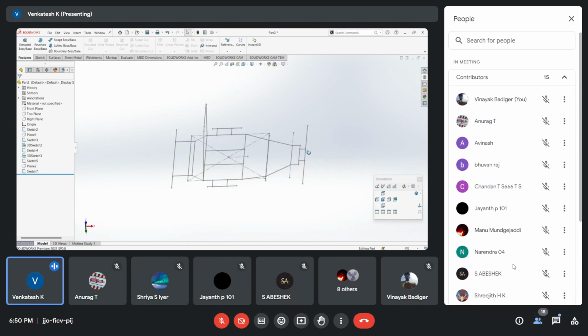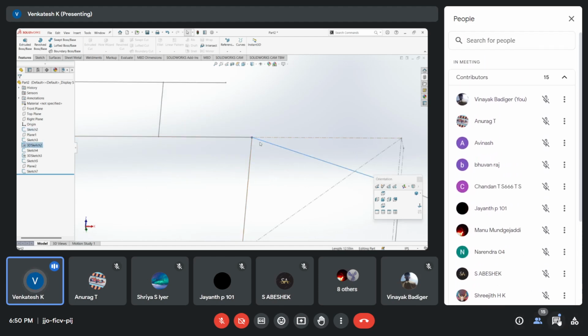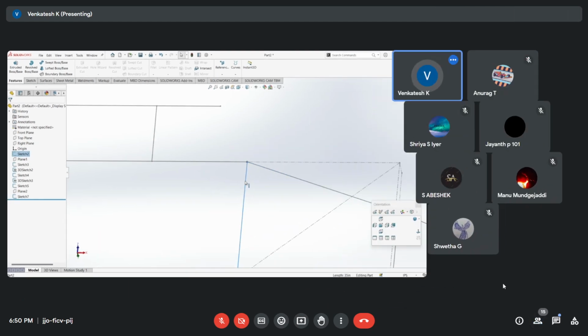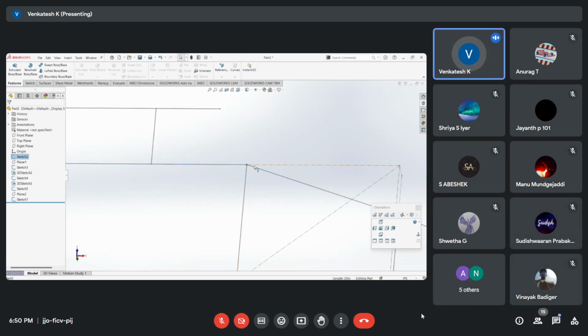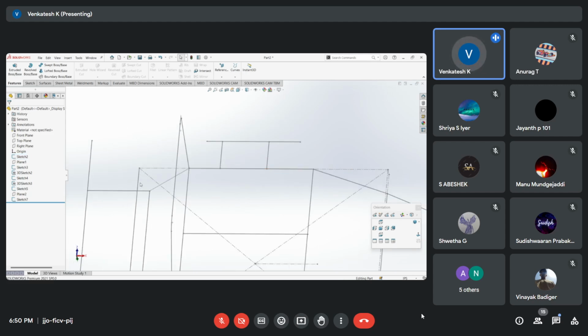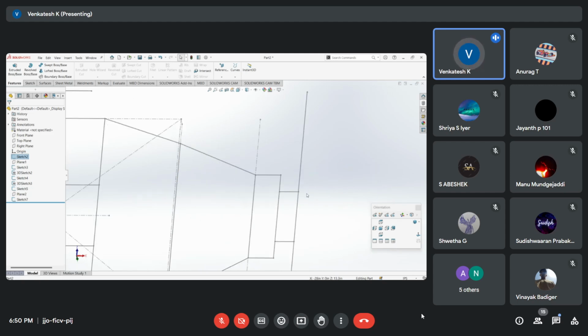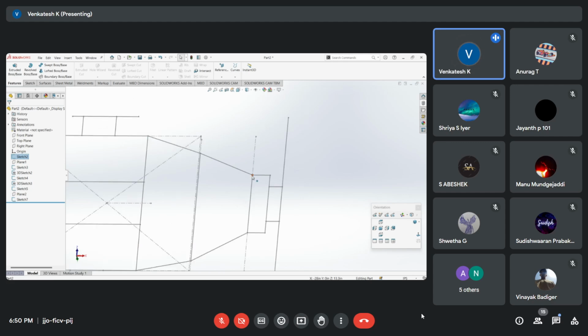All other parts are also supposed to be fillets. This joint is a fillet. Only this line is going to be welded with this single pipe. That goes the same over here, here, here. Here, this is the start of the pipe. This is the point where the pipe starts, and this is the point where it will end. This full thing is again a single pipe.